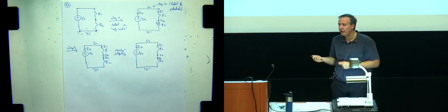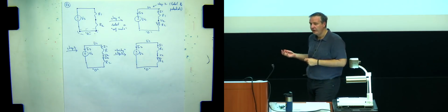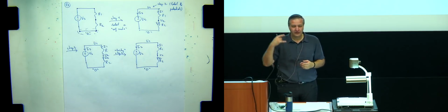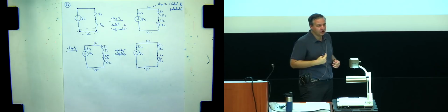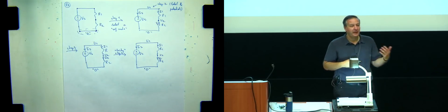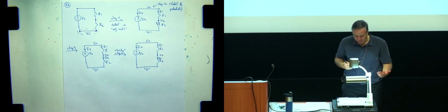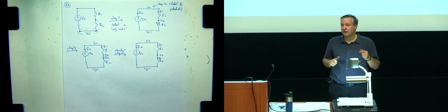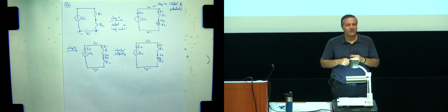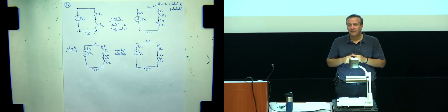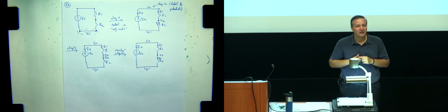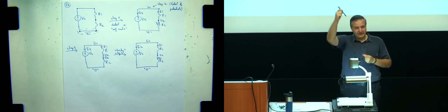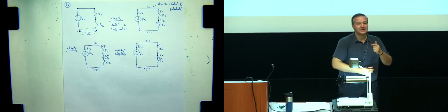But because we've already added the currents, we now need to be careful that the orientation of the voltage of the element we're adding follows the passive sign convention. So what is the passive sign convention? The current enters the positive or exits the negative part.